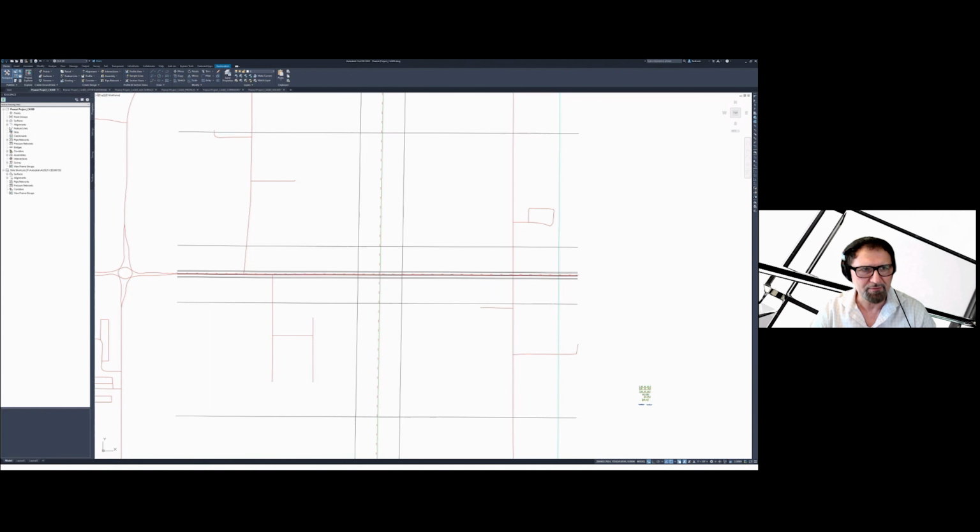So for those two, obviously we designed two centerline alignments, for mainline north and sideline east, because the mainline is in the north direction and the sideline continues to the east. From there, I also have some offset alignments created on the sideline and used for corridor modeling for the mainline and the sideline as well.